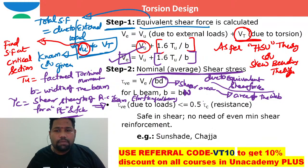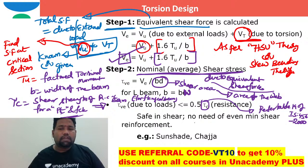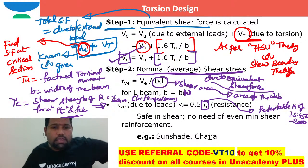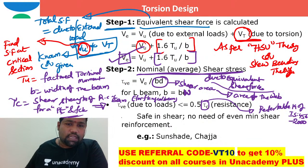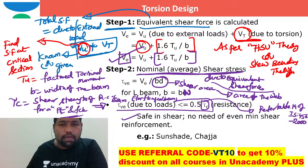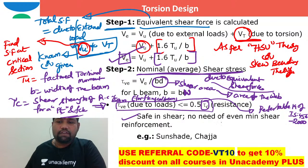If you want to see the same thing in terms of the code of practice, refer to Table 19 of IS 456. But generally in competitive examinations, they will provide this value of tau c. In this particular case, the cross section is safe in shear when tau V is less than or equal to tau c, and there is no need of even minimum shear reinforcement.